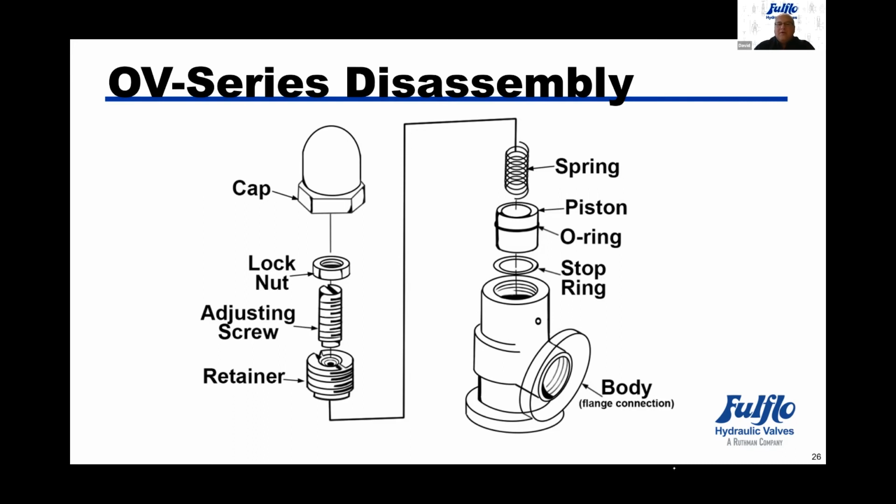And you can also note there is no holes in the piston itself, as it's a solid plunger up and down. Here we don't have to worry about any fluid getting up into the cap because it won't even be getting up into the spring chamber at all.